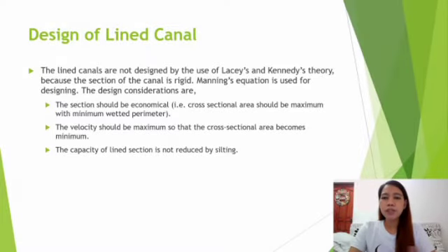So now let's proceed to our last method, the fourth method. We are going to design a lined canal. For lined canals, we will not be able to use Lacey's and Kennedy's theory because the section of the canal is rigid. So Manning's equation is used for designing.